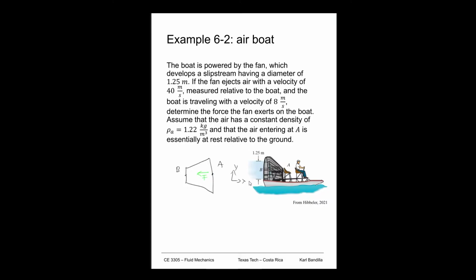In this case, the y direction doesn't make a huge amount of sense, because there's nothing there in the y direction. But what are we going to do? Well, let's figure out some stuff. We know that we're going to use the linear momentum equation, so we have to think about what the different velocities are. Very importantly here is that our boat is moving, so that means our control volume is moving. So we have to take that into account, especially for the flow of air that's coming in, right? Because it's not zero, it's moving with 8 meters per second.